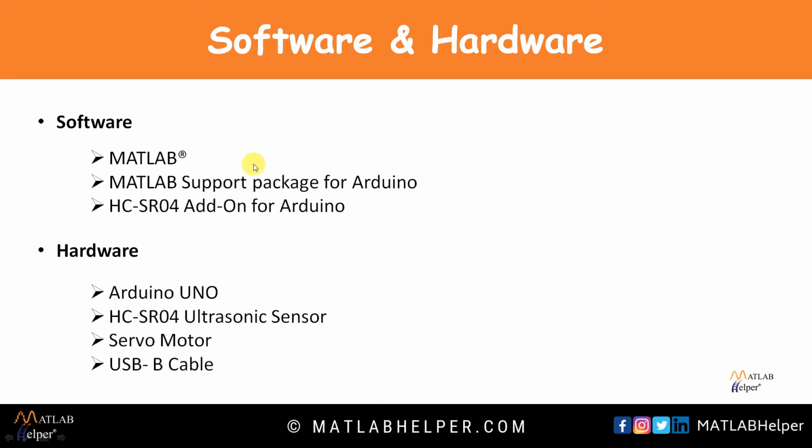So these are the software and the hardware that we will be needing. We will need MATLAB, the latest version, a version greater than 2016, the MATLAB support package for Arduino, and the HCSR04 add-on for Arduino. In terms of hardware, we will be using an Arduino Uno, that is a microcontroller, an HCSR04 ultrasonic sensor, a servo motor, and a USB-B cable for connecting our system with the Arduino Uno. So this was all about the software and the hardware that we will be needing for this webinar.